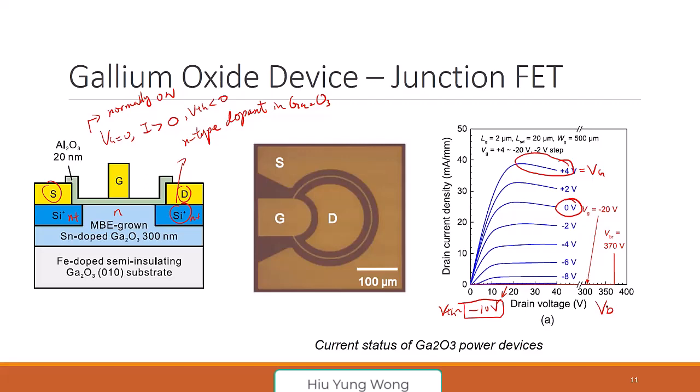Why? So I have a resistance, right? If I have resistance, I should be low at the beginning already. Why when I increase the drain voltage, the resistance is larger? The heating. The heating, very good. When you increase the drain voltage, V times I increases, so heating increases. As a result, your mobility decreases. And that's what we call self-heating.